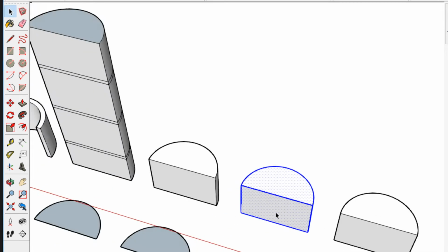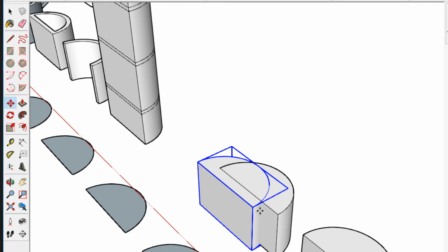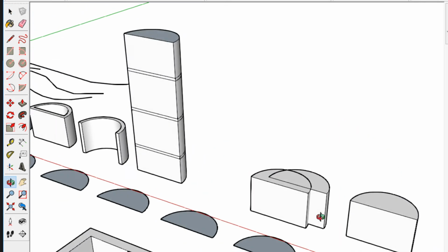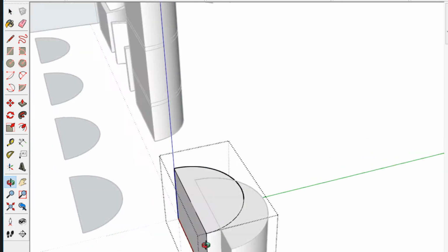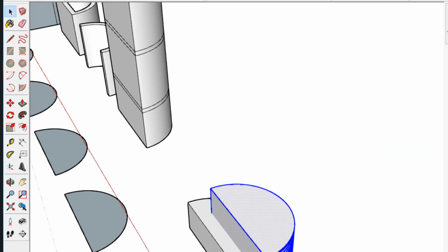But when it's a group and it tries to go here and I try to remove it, nothing happens, because it's like you have your own model inside a group. You can even go inside the group by double clicking and edit inside the group, and this one will not get affected. See?